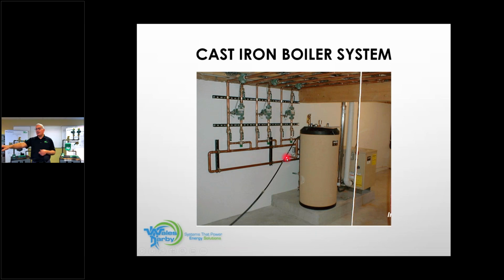It's possible, but probably not. So we could bring this down to 2 temperatures. Taco does make an i valve, which is an outdoor reset mix valve that'll fit within the same footprint as that standard 3-way valve. So now we can add even more efficiency and comfort to this system.